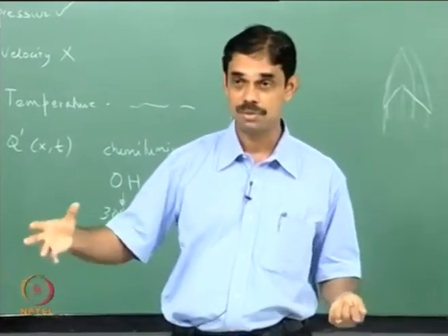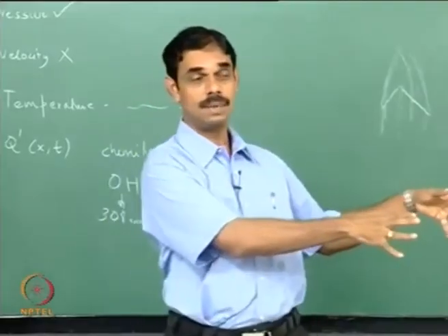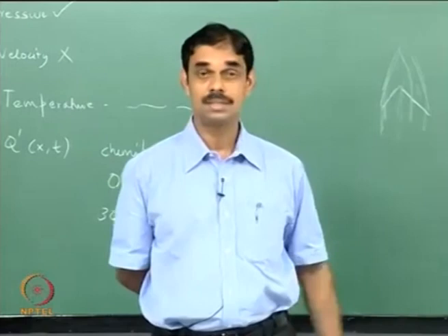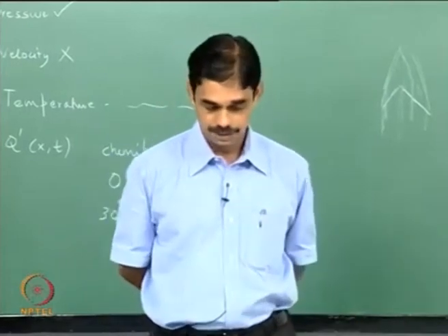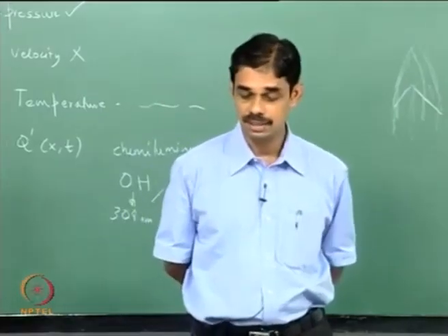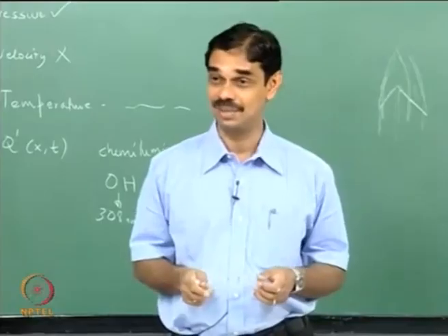So it's like using the devil to fight the devil, and then absorb the sound which is generated by heat release at some other place, by this heat release, and try to take it out. So this is possible and it has been practiced, but for ideal actuation a fuel valve should have a linear response to allow linear control theory to work.